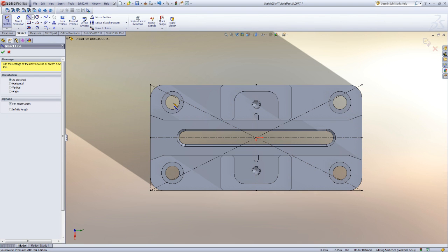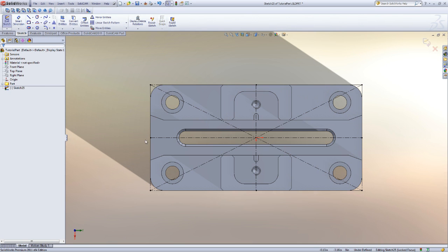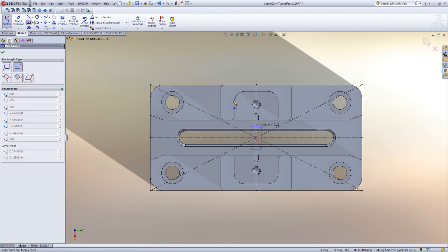All of these center lines that we just created all end up pointing to the center. And like I said, this part is drawn on center, so it's easy to see that we're correct with what we've done. Now, once we know the center of our part based off of its extremities, we can draw our stock material from center.